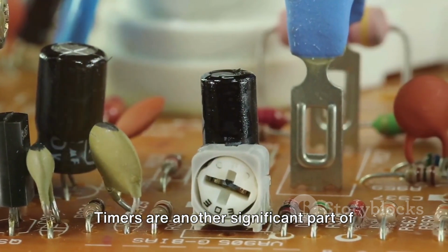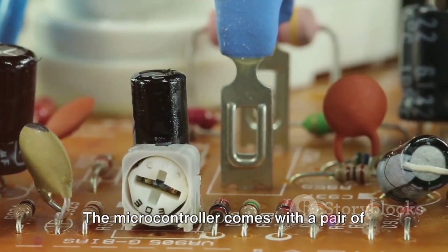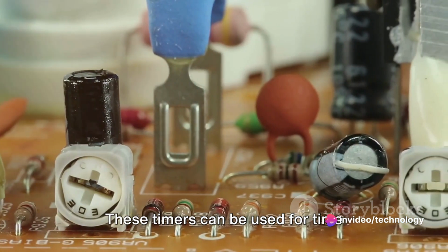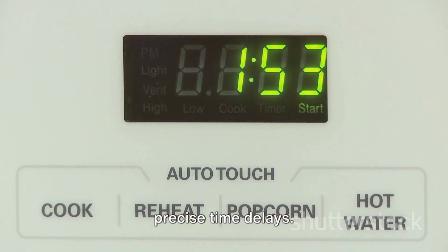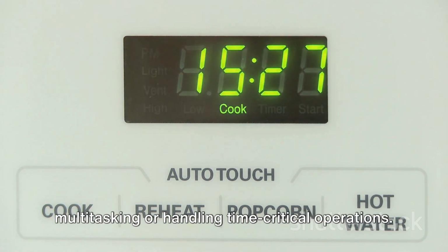Timers are another significant part of the 8051 architecture. The microcontroller comes with a pair of 16-bit timers/counters. These timers can be used for time management, event counting, or generating precise time delays. They can also be configured to generate interrupts, which can be useful for multitasking or handling time-critical operations.